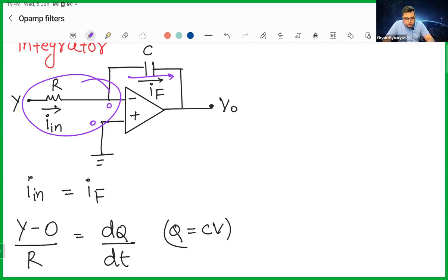If V1 and V2 are 0, how can the OPAMP amplify the signal? I do not get you. You're saying that if these 2 points are 0, 0, then how can it amplify? It is not amplified. Nothing is being amplified here. It's acting as an integrator. It's just integrating the signal, and it will add some gain into it.